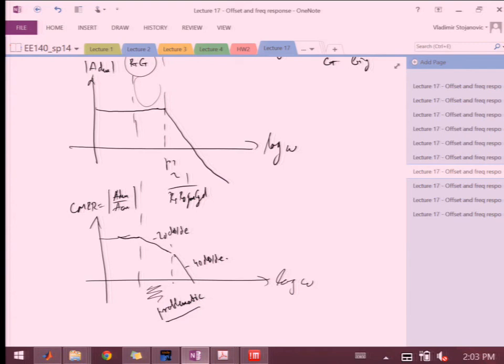And then with it, these poles actually move out. And we're going to use that feature to add a lot more CC cap to be able to split poles and start doing something that's called compensation in the amplifiers. So for the next lecture, we're going to do compensation and also explain that a little bit more. That's something also you'll be doing in the labs as well. Okay.